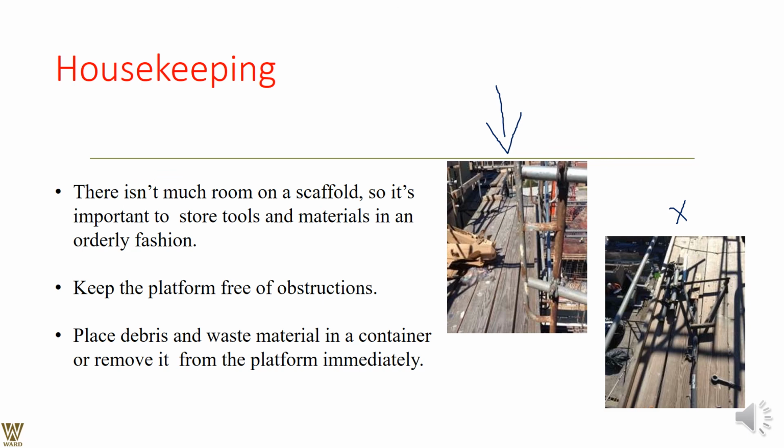It is important to store tools and materials in an orderly fashion at the required place. Keep the platform absolutely free from obstruction. Place the debris and waste material in a container and remove it from the platform as quickly as possible. Any debris, wastage, scrap, or trash that comes out at the end of your work, remove it and throw it out.